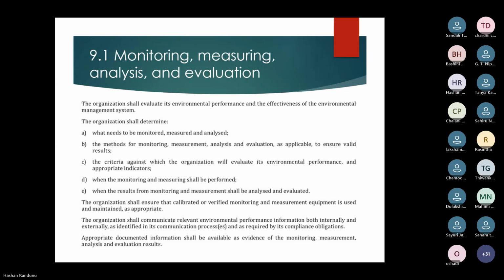But if you take measuring, measurement is the process to determine a value, right? You need to measure the pH of the treated wastewater. You need to measure the residual chlorine level of treated wastewater. You need to measure COD and BOD of treated wastewater. You need to measure the boundary noise. You need to measure the smoke opacity of the emitted gas from your boiler. So those are the measurements.